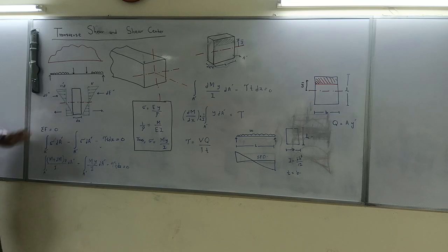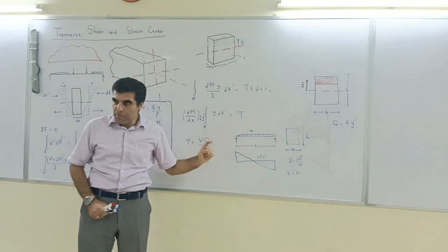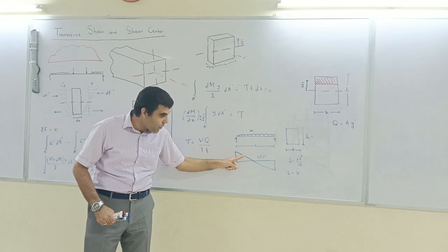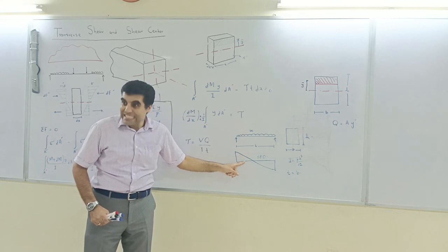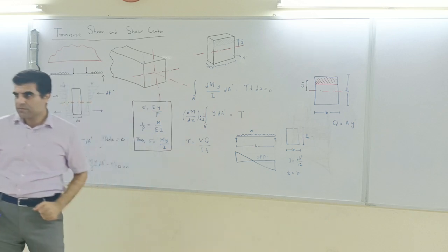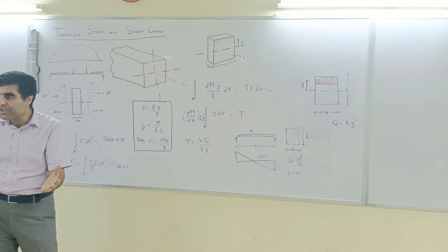So similarly, your shear, as you come down, is also changing. Although the whole cross section is subjected to one shear force, a resultant shear force, which you determine from your shear force diagram. The shear which you get from this shear force diagram is the resultant shear of the whole cross section.